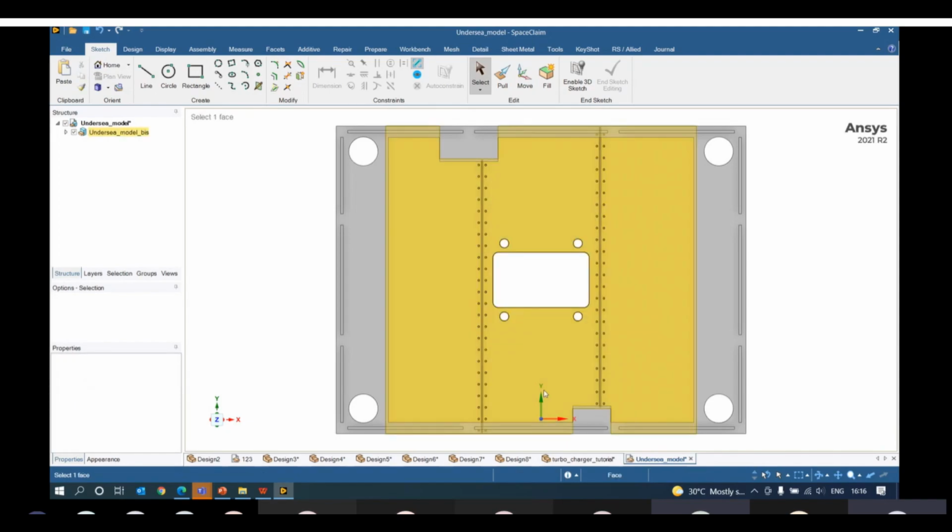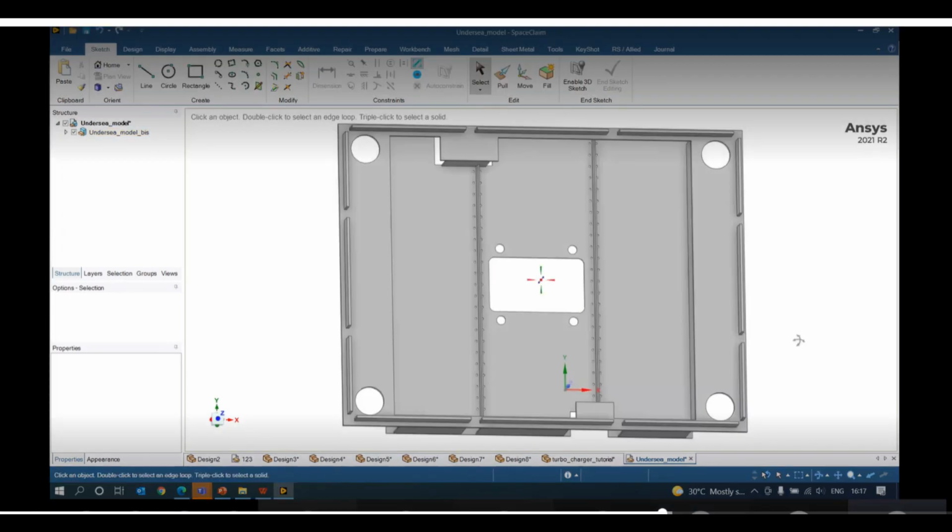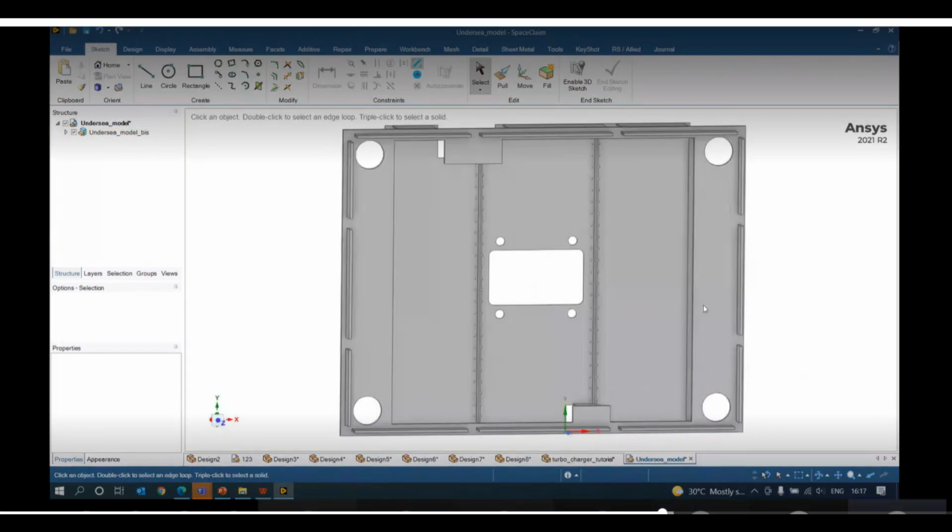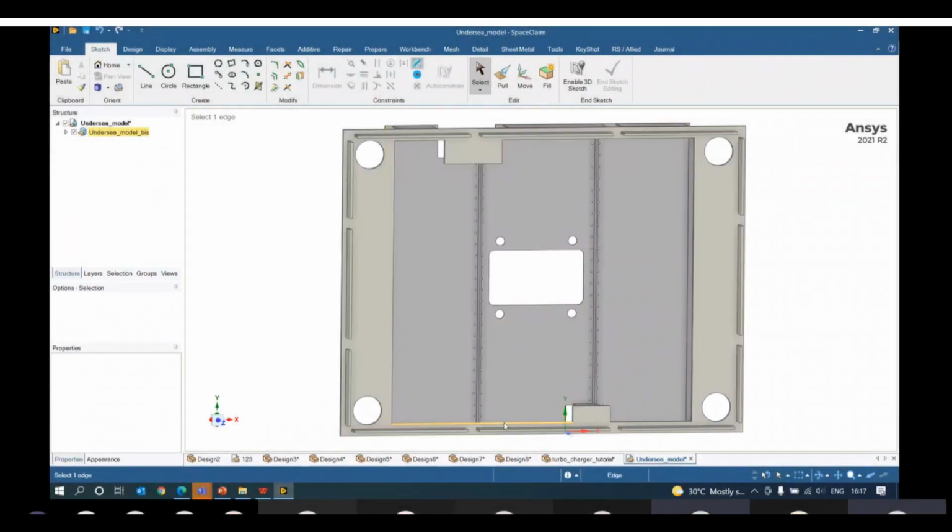Next important thing, there are small holes existing. Now when we work on simplification of your geometry, you can have a complete assembly, but when you want to solve it for just a component, you do not need all the other components with you. So we'll remove all the other components and all unnecessary things and try to solve. In case of me solving this problem, if the small holes are not playing a vital role, I'll just remove those.